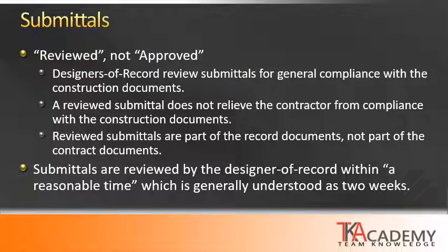The manufacturers of these will submit their proposed fabrication, their product data, material samples, and so on to the general contractor, who then turns around and submits this to the architect for review for general compliance with the design intent indicated in the construction documents. The key takeaway here is that it is reviewed, not approved. So again, the architect is reviewing for general compliance with the construction documents.